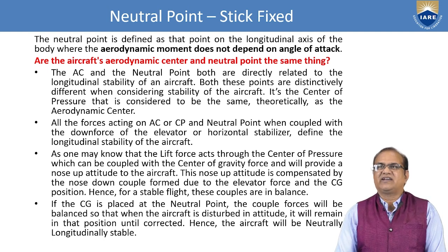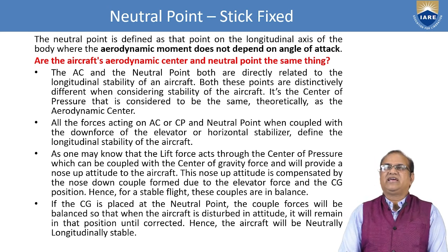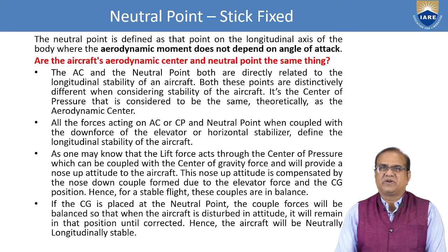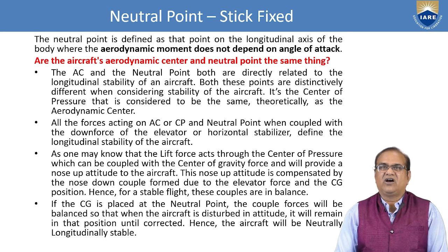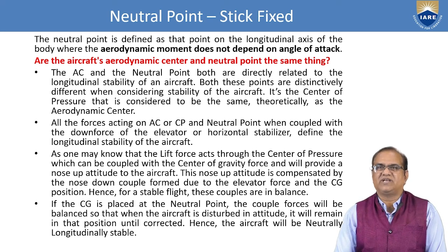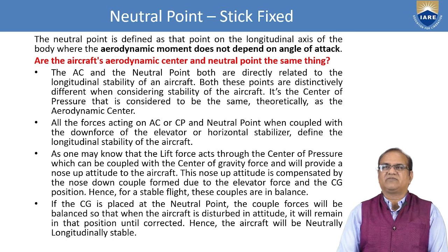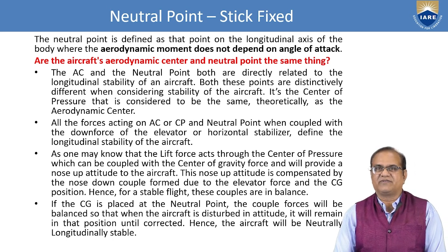Both these points are distinctively different when considering stability of the aircraft. It's the center of pressure that is considered to be the same theoretically as the aerodynamic center. All the forces acting on the aerodynamic center or the center of pressure and neutral points, when coupled with the down force of the elevator or the horizontal stabilizer, define the longitudinal stability of the aircraft.